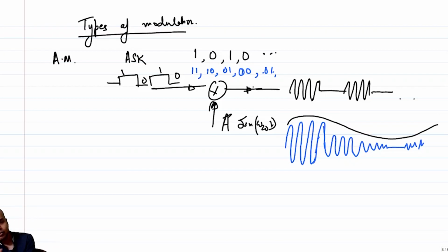So this envelope you feed to the PA, correct? Now the thing is, you do not directly feed it as is. You also push this through some sort of filter, because otherwise you get abrupt endings of a symbol, right? Abrupt ending means that you develop high frequency components. So you put another set of filtering, a smoothening filter, and then you send it off. Okay. So now, we also know that we need not necessarily always send information in terms of amplitude. We can send information in phases, right?